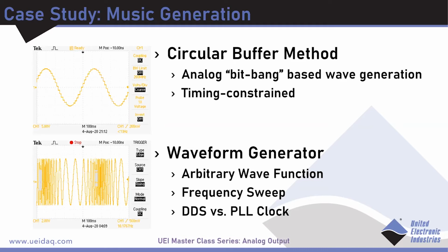However, in other applications, getting away from music a little bit, PLL mode might be a little bit better. So PLL mode is our most precise mode. If you have a pretty standard frequency like 400 hertz or something that you need to output, but you need to output precisely and repeatedly, then you might use the PLL mode as it's more of an analog process and therefore more precise in terms of the feedback and the rise time and so on.